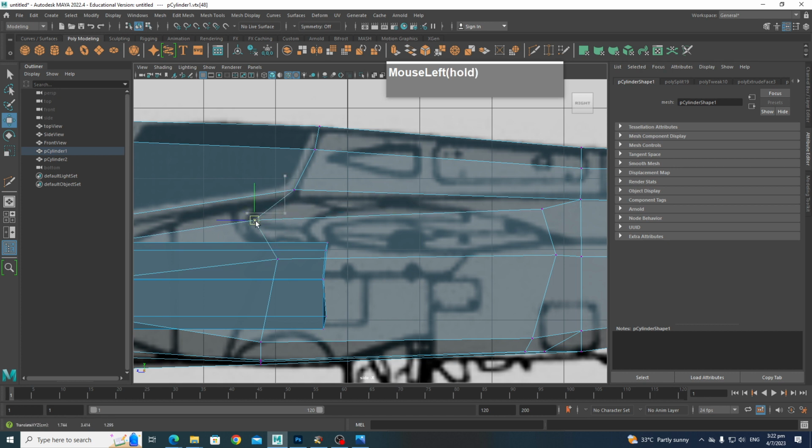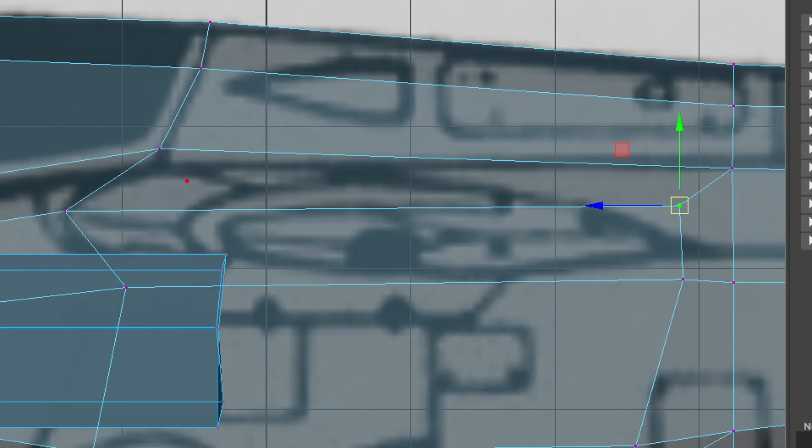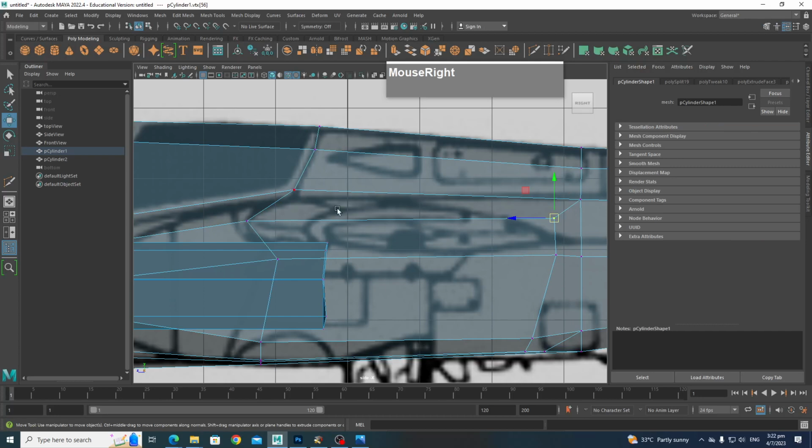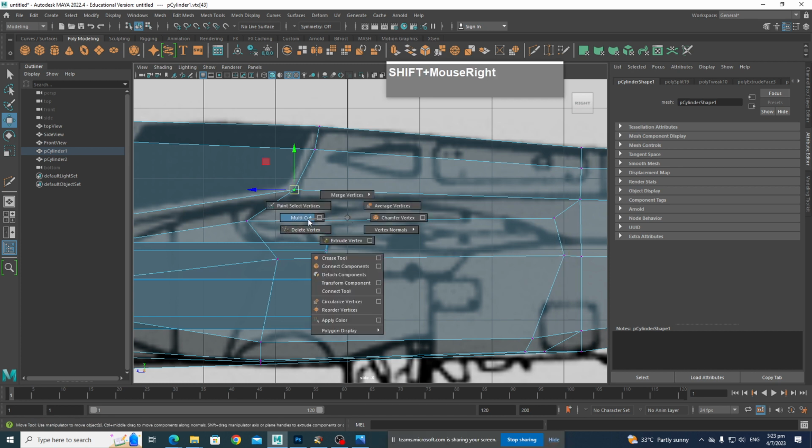So what I'll do is I'll push this face up here so that I have enough detail to pull out the wing. You can see the wing here. It forms this aerofoil shape very nicely. So I will make sure that I have enough faces to actually create that shape. This one maybe I have to pull this one back. Okay, I'll insert one more edge loop here.